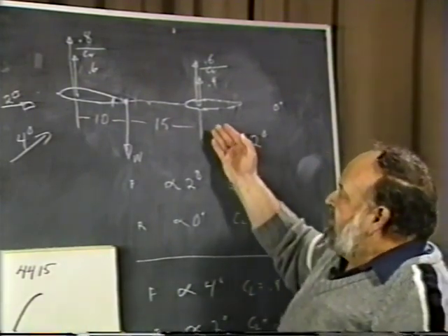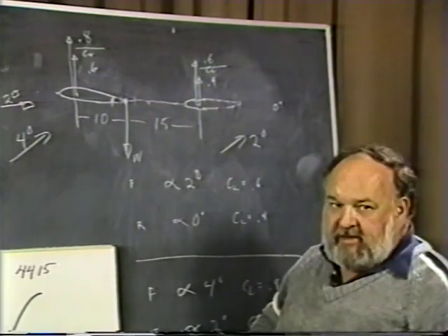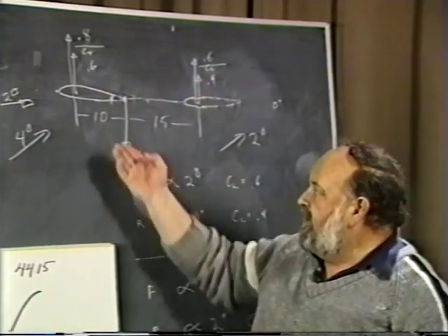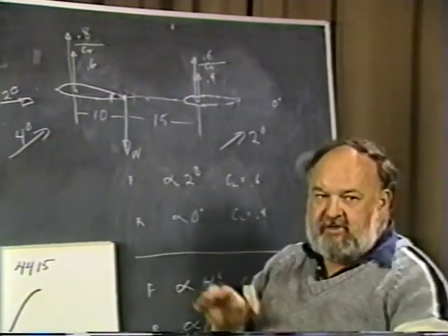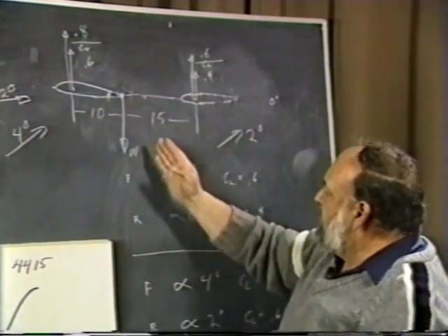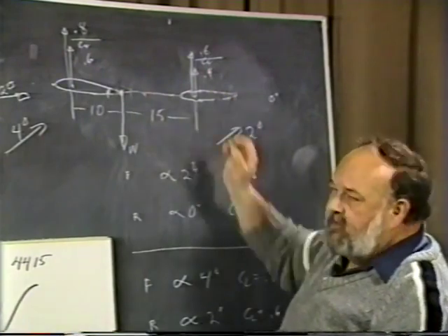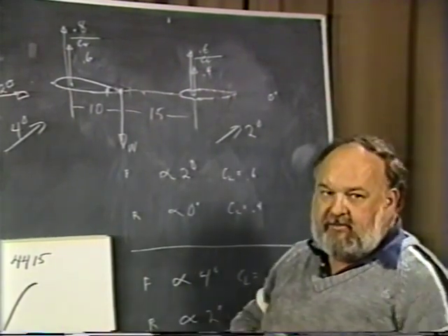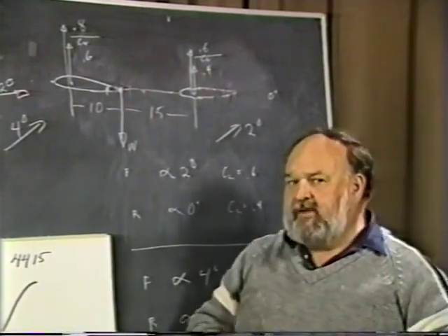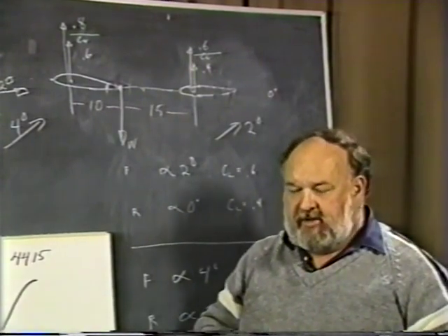If we actually made this wing smaller now, so it didn't have the same amount of area as we had in the beginning, where the two were identical tandem wings, then we'd have to keep moving this further and further forward, because this was a smaller total lifting force, until we were totally balanced. So that's really what it boils down to on any particular airplane.